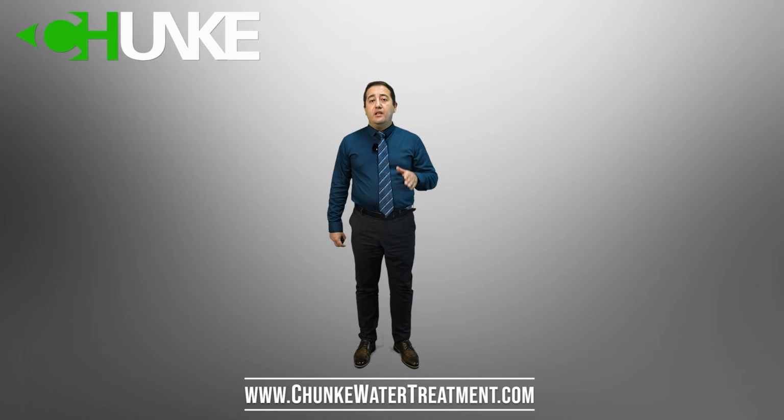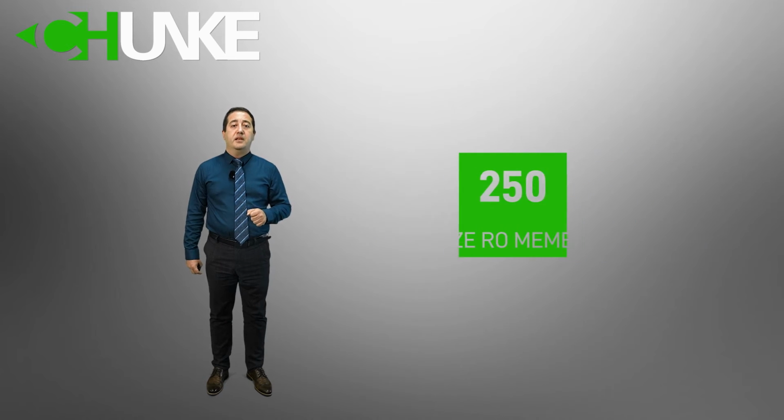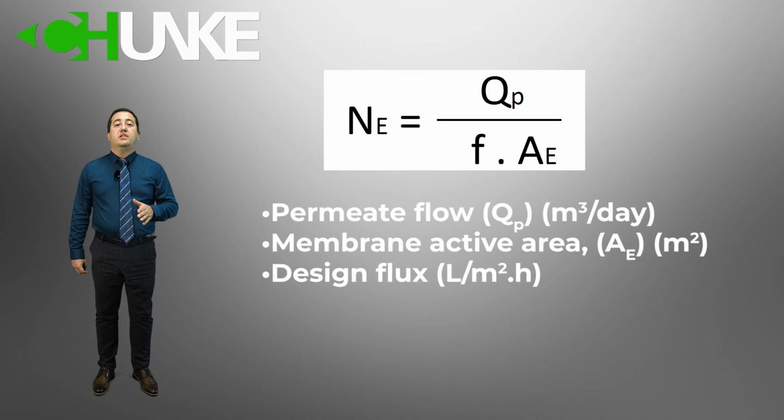Don't forget, if you design a reverse osmosis system of 250 to 2000 liter per hour, you should use 4040 size element. For 3000 liter per hour and more, you should use 8040 size element. To calculate element number, it means reverse osmosis membrane number, we use this equation: Ne equals Qp over F times Ae.